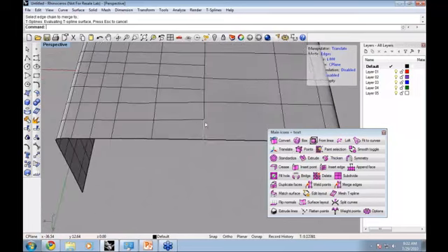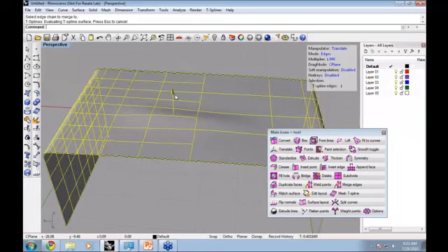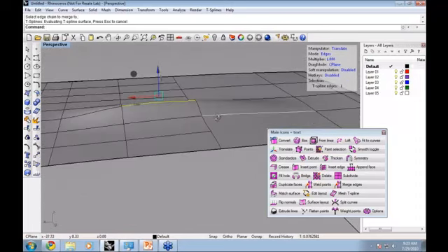Coincidentally, these points right here, you see how this point tees off. That's still curvature continuous C2 smooth there. That's where T-splines get their name, is from these T points, which is how you can end local detail in the middle of a surface.